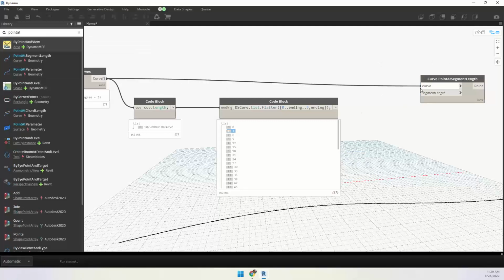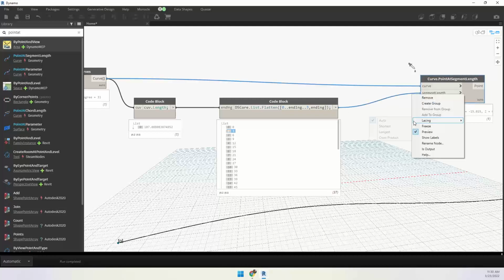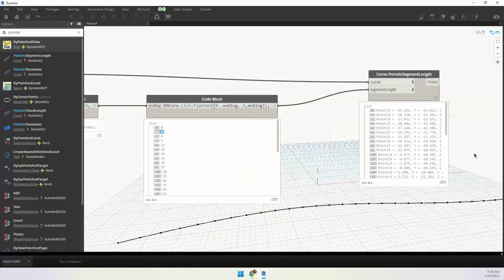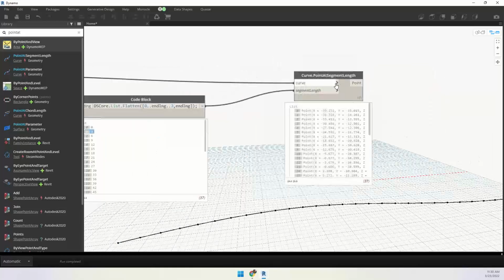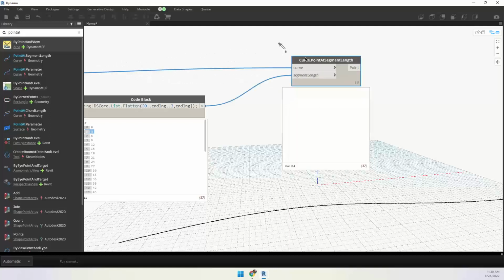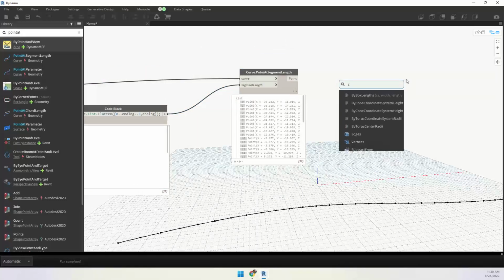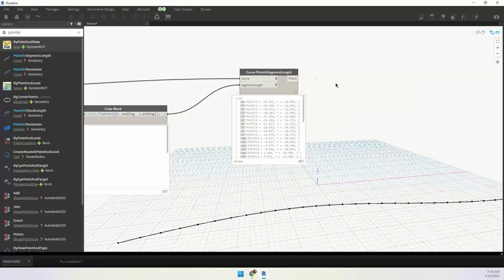So when I connect the curve to this, and the segment length is this, longest lacing. The same curve, I want to play with the same curve with the number of elements. So, same longest lacing. So I have a total of 37 points now. Okay, let me check whether they are right or not. Let me use Curve.Length, because they are in a different direction, so there would be some sort of tolerance.